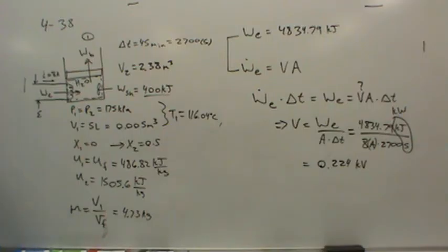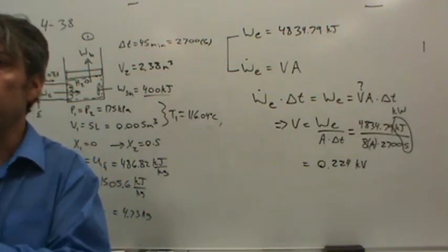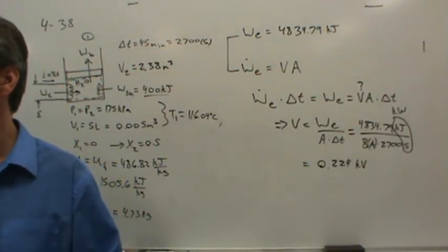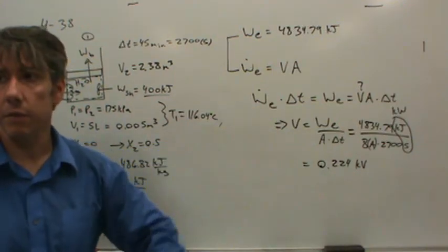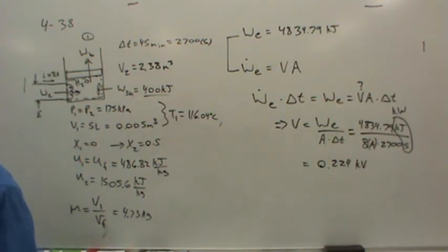Any questions? For that second method, you would use the enthalpy of the system instead of... Yes, for the second method, the internal energy and boundary work would be combined into enthalpy. So you use H1 and H2 instead of U1, U2. Then you wouldn't have to mess with P delta V. Okay, anything else?